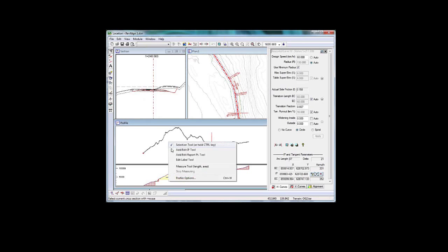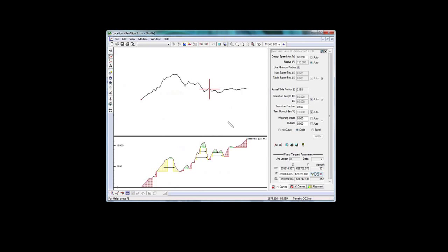These are all tools that come with the road design package. Haven't shown you anything about the Optimal yet. Okay, so we've got a horizontal alignment. We want to build a vertical alignment. The process manually is to start by designing vertical intersection points in the profile window. I'll just show you a couple.